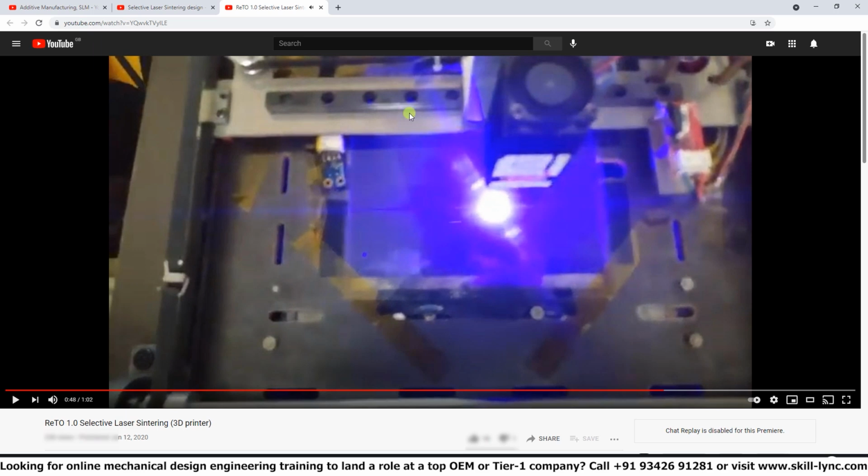So I just want to mention, as you can see, there's sort of 3 axes of motion over here. The workspace, or the build plate, moves down. So that's in the vertical axis or the Z axis, right? Here, the laser itself, the laser module, is attached horizontally from left to right to a motor which moves it left and right.